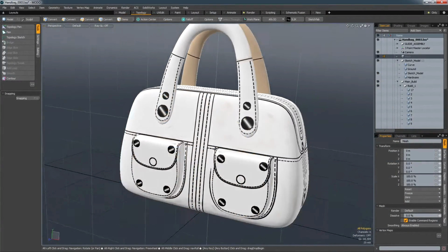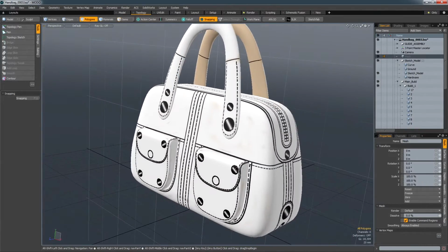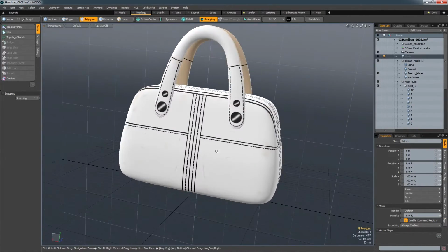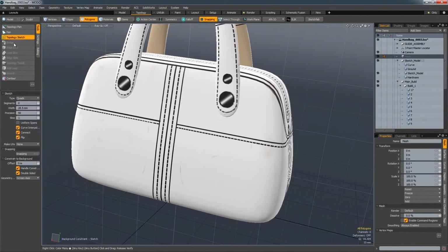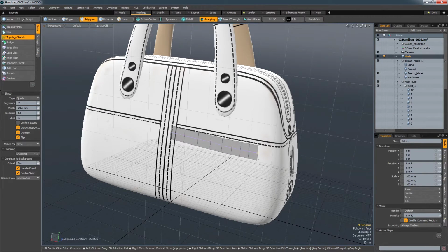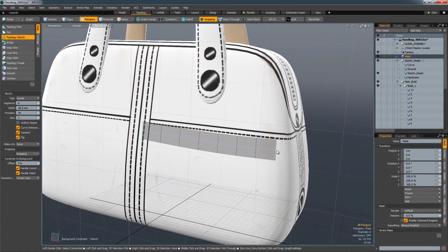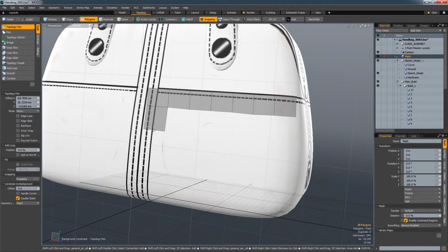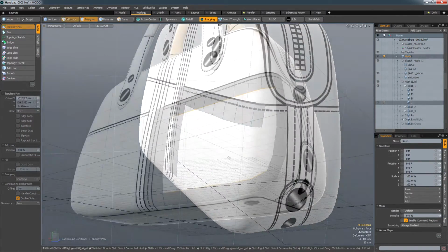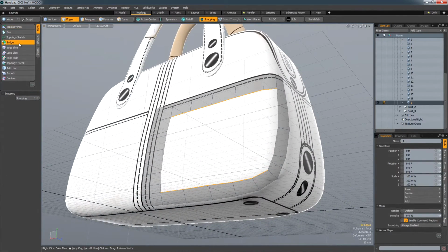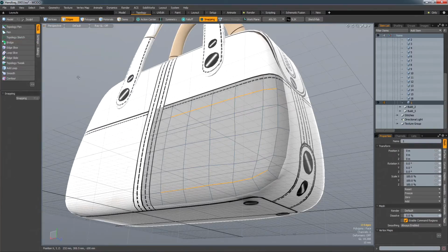But if you do want to take the model further, then this sketch model is invaluable. With the location of trench and stitch lines already defined, it can now act as a guide when building more accurate geometry. A good starting point is to follow the lines defined in the sketch with the Topology sketch tool. This allows you to quickly paint new geometry across the reference geometry. With those lines defined, you can then bridge between them to form a panel.